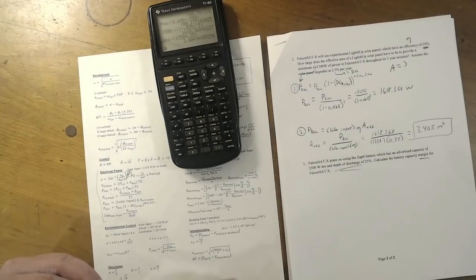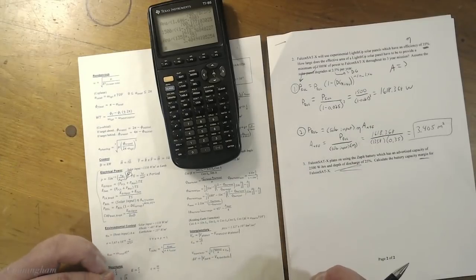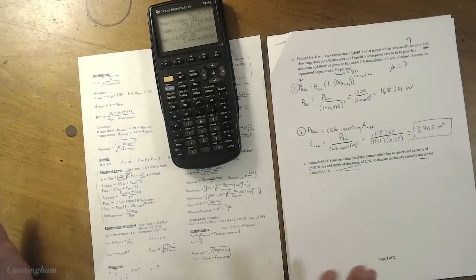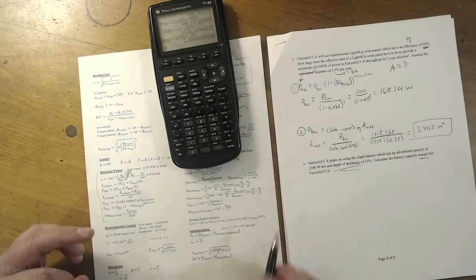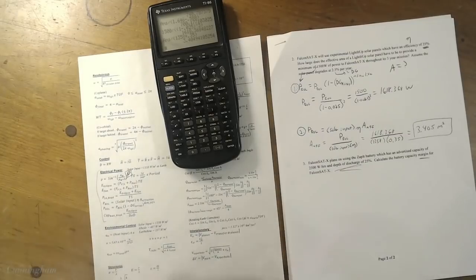So what we're saying is we're actually going to need a much bigger battery. So if we just discharge at 25%, 25% of whatever battery we choose is going to power us in eclipse. That's our design constraint here. That's what we want. We want to give ourselves like 75% extra margin in eclipse and in sun. Anyway, so let's just crank through the math.